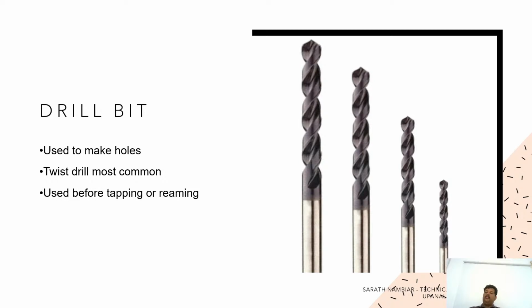If I drill a hole of 10 mm, will I get exactly 10 mm? That's a question some people have asked. In most cases, no. There may be a slight variation. So the surface finish may not be good. So drilling is only the first step. If we need accuracy, we won't stop after drilling. So first we use the drill bit for basic drilling.